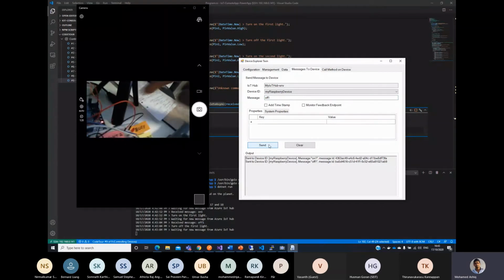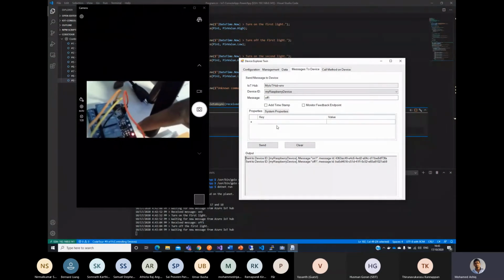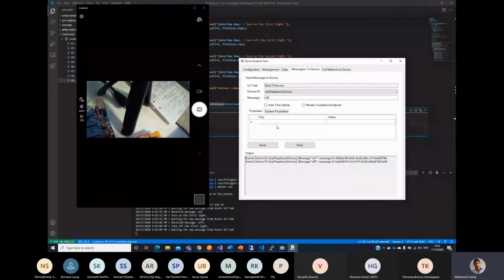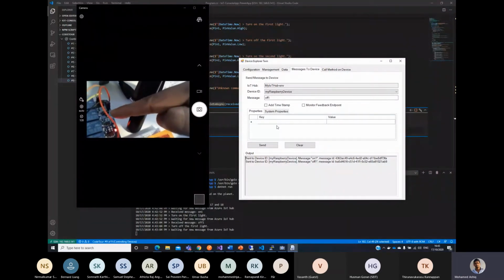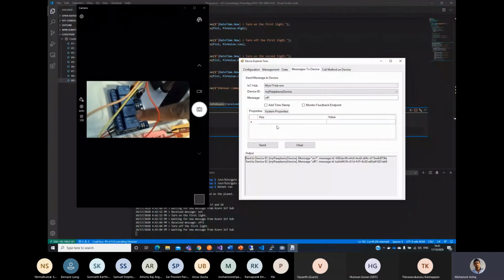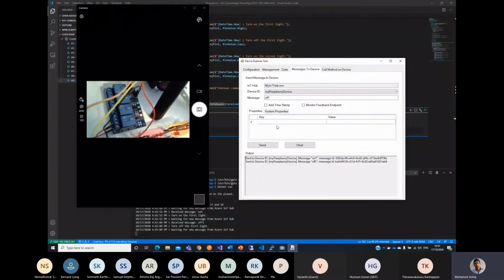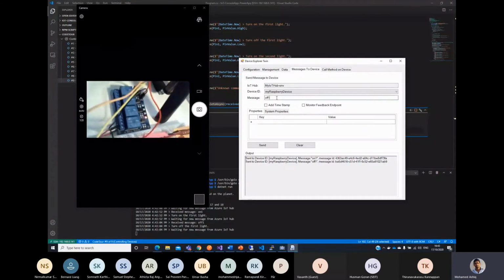Light number 2 is connected to the relay module. Whenever there is a signal on the GPIO pin, it activates this relay, and with the help of this relay you can control a high-powered device. But here, I'm again controlling the relay board, sending the signal from the IoT Hub, with which I am turning on a different LED connected to the relay module. So you can look at my screen.